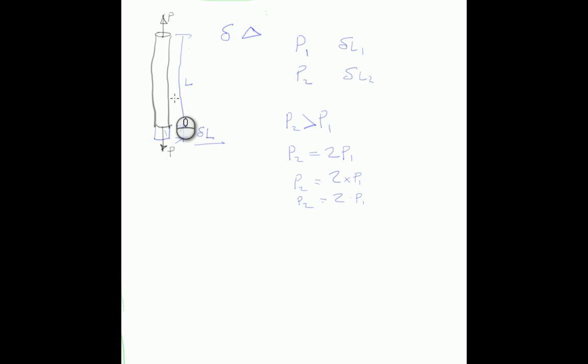Now, for this particular piece of material here, we could increase P1 to P2, and we would find in this particular experiment that we conduct that delta L changes. If we double the point load P, we will find that we'll also double the change in length, so that this value here, if we have a P2 now,